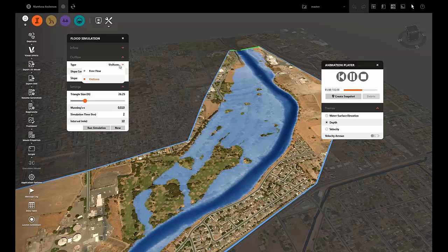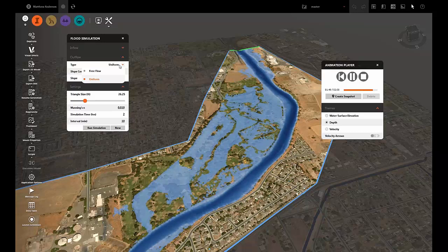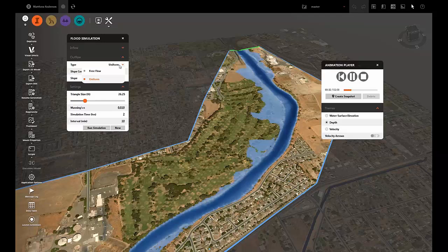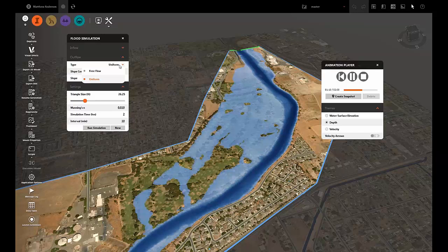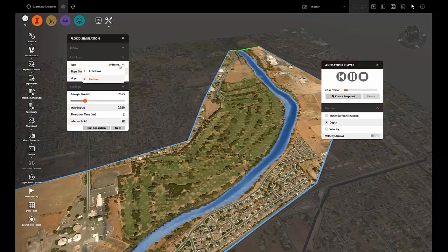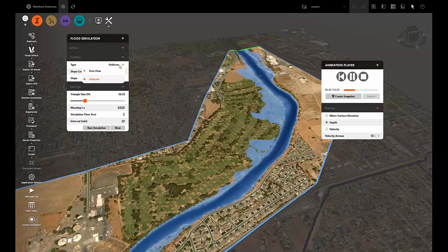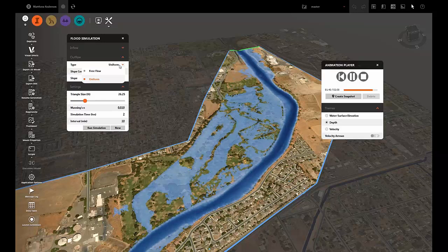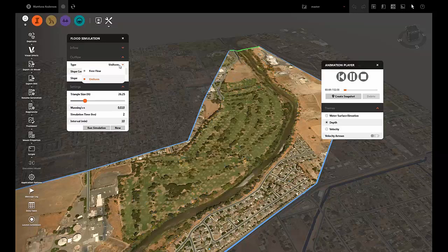So when you have water getting to the boundary, the model will use the relationship between stage and discharge for the whole cross-section based on the uniform flow calculations that were done, and will use that relationship to impose the combinations of water depth and discharge for that condition. So they're very different in that sense.